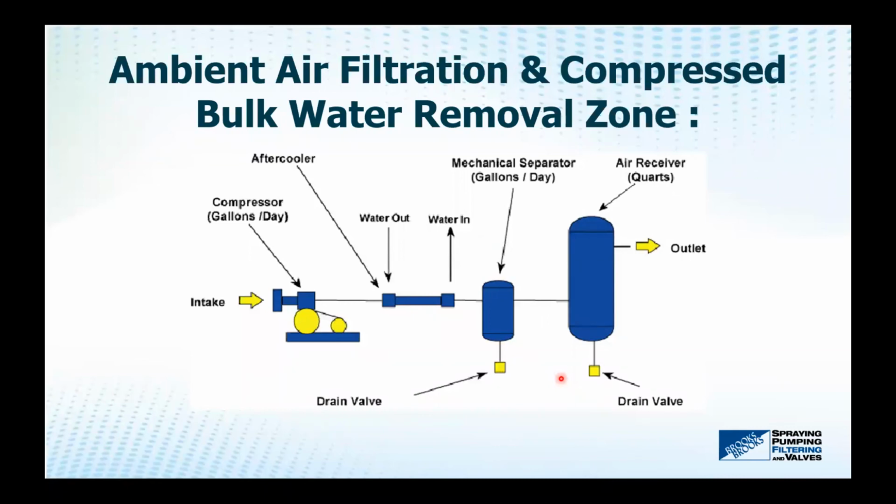Zenon, if I might add, the arrows, and this is my fault, should be reversed on that water-cooled aftercooler. Correct. The water should be coming in downstream and leaving upstream, countercurrent to the direction of the air flow. Good point, Russ. I'll have to modify that for the next presentation.